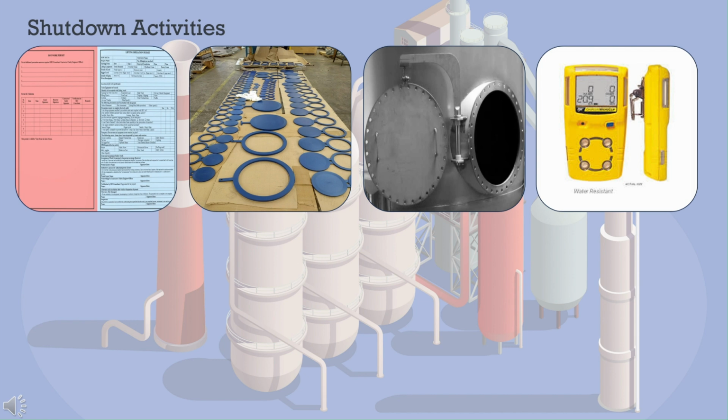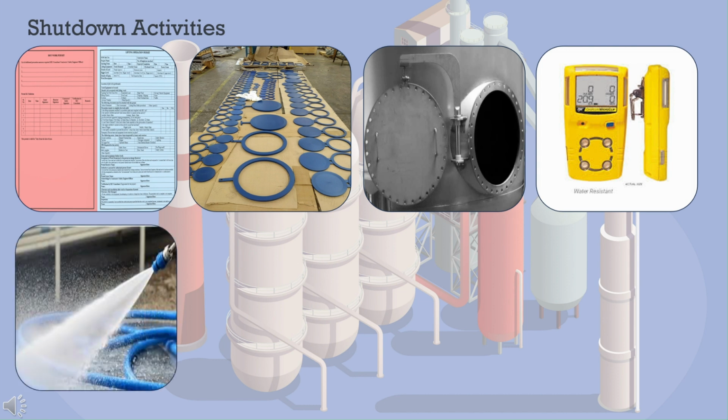Carry out pre-cleaning inspection to assess fouling and damage of any section. Perform manual cleaning or high-pressure cleaning of internals as required, typically cleaning from top to bottom and covering nozzles at the bottom to avoid damage. After cleaning and vacuuming out dirt, conduct an acceptance inspection.